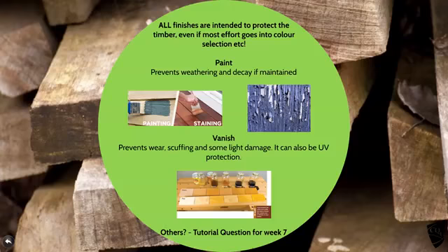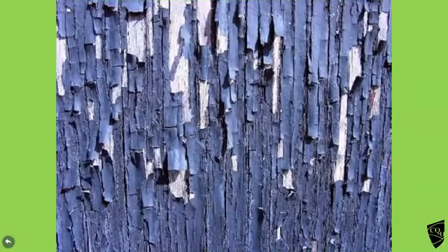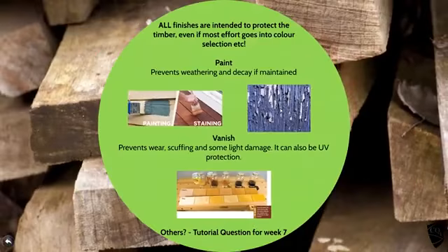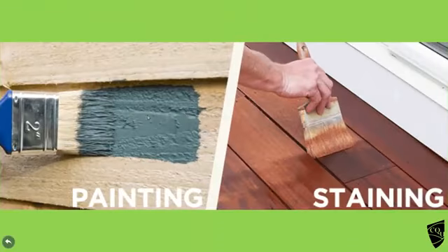If you don't maintain the coatings, they break down. To me, that looks like a very old paint. The way it's faded, it's probably a lead-based paint, which were fantastic. But because people kept licking and chewing them, they've now been banned, apart from very special heritage uses. The two things you can go for, you can paint it on, and that's a rough sawn cladding by the look of it, and that's going to soak straight into that, as long as it isn't too damp. And staining, the same thing. Staining penetrates deeper than paint does normally. And of course, staining lets you change colours, but they both act as a protection, a type of preservative.